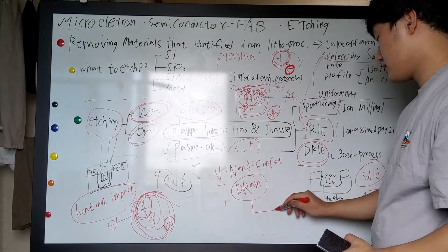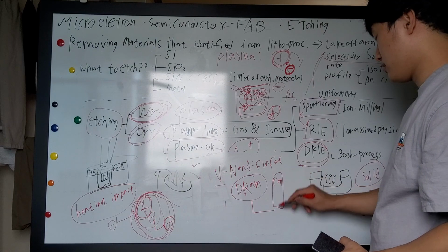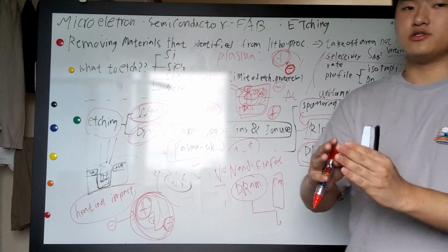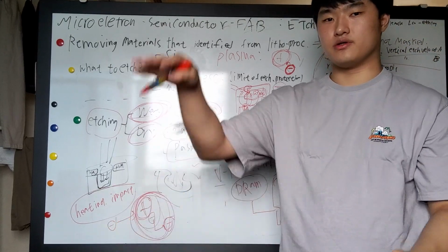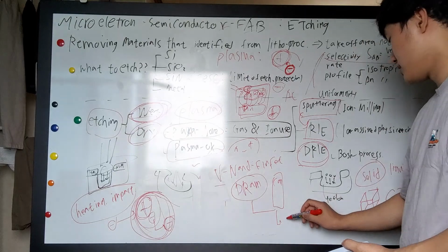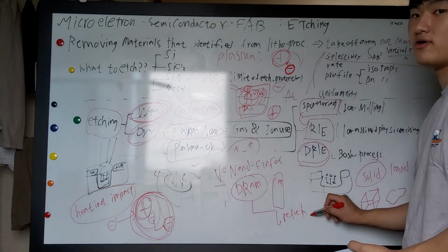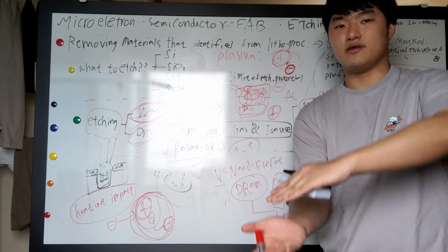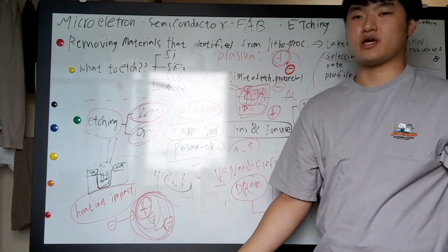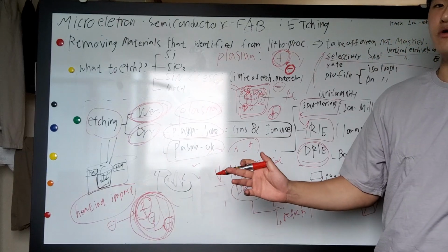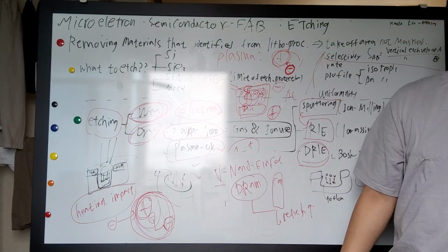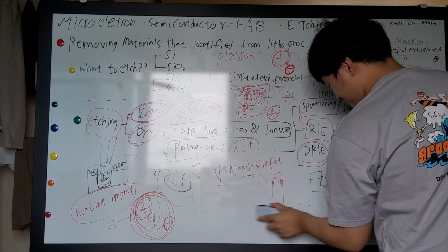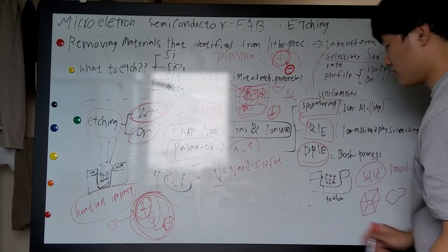Well, the hole can be said to act as the capacitance here. For the capacitance, the larger the distance, the more the capacitance will be downsized, which means the refresh frequency will be faster. But if the distance is small enough and the height is long enough, then the capacitance is very big and the DRAM doesn't need to refresh as quickly. And so for the vertical channel,